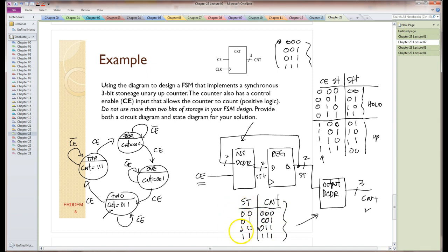Now the way we assign these states is somewhat arbitrary. We could have assigned them some other way using 2 bits, but it's easy to keep them in binary count order. Nothing real special about that. But the important thing is that this counter is going to count in this sequence. This is what the outside world is going to see right here, even though the inside world is counting with a standard binary count. No one knows about that. The output of this circuit is the Stone Age unary count, and that's all the outside world sees. So this is a classic circuit.